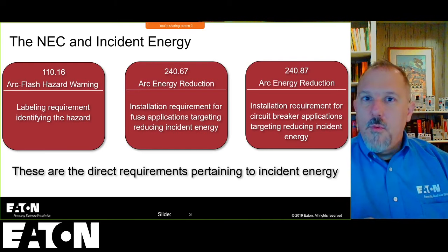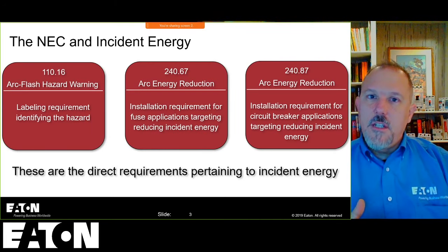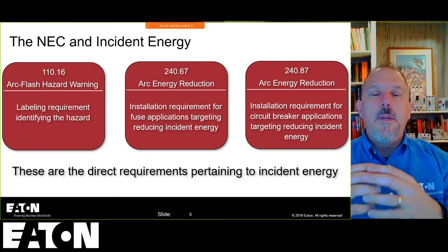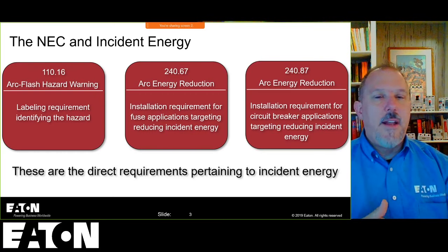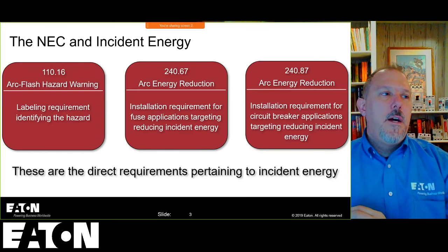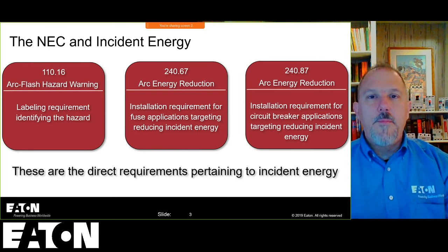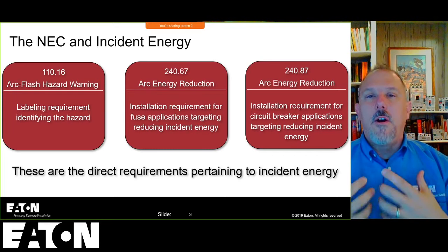Well, the problem with an ungrounded system is those transient voltages, right? I have one, and they could be caused by many things. I could have had a ground fault. I could have had some sort of electrical disruption that would cause severe overvoltages, and it would damage motor windings and all this other good stuff.